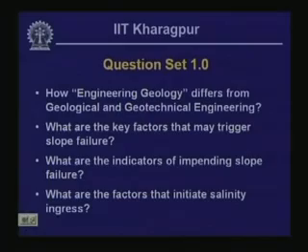The second question I asked was what are the key factors that may trigger slope failure. Two of the major factors that cause slope failure are loss of strength, loss of shear strength of the material of which the slope is comprised. The major reasons for the loss of shear strength is basically